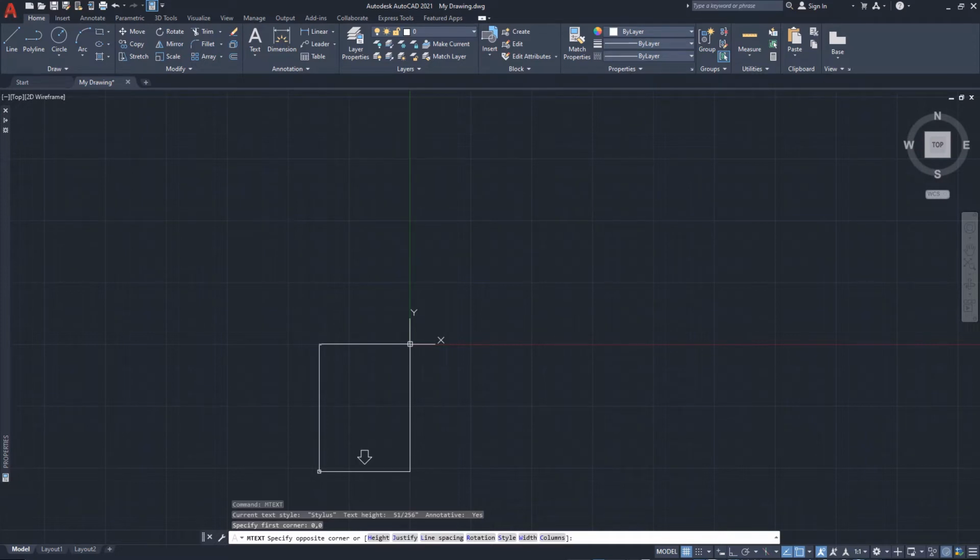We also see several options available to use in the squared brackets. In this instance, let's type in the command line the @ symbol. Recalling from our previous video, the @ symbol in English words is saying from where I started go, and from where we have started is the coordinate point 0, 0, followed by 2, -1, and hit the Enter key.